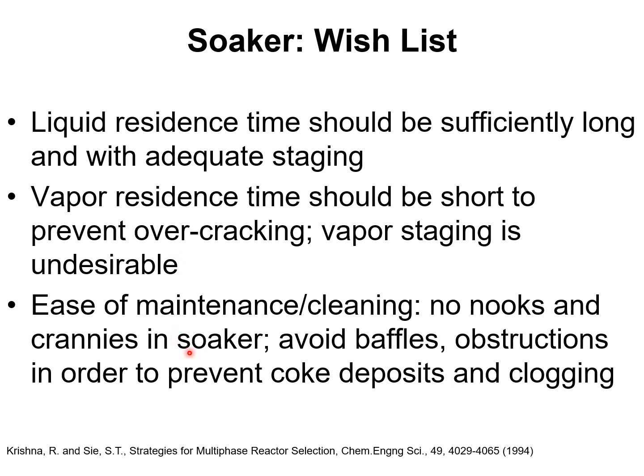Now, in the visbreaking process, there is a tendency for coke to deposit on the walls of the vessel, and the internals, such as perforated plates, are susceptible to clogging. Therefore, for ease of maintenance and cleaning, there should be no nooks and crannies in the soaker. We should avoid baffles and obstructions in order to prevent coke deposits and clogging.